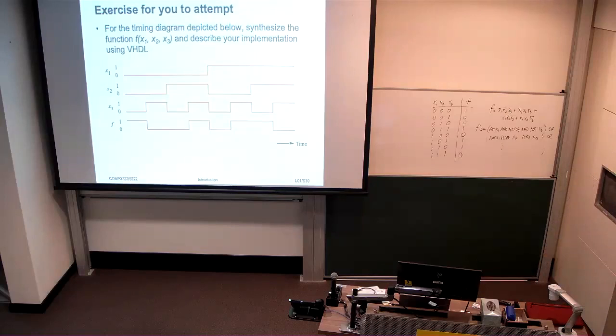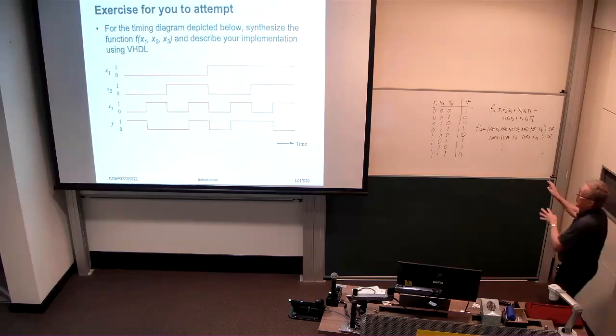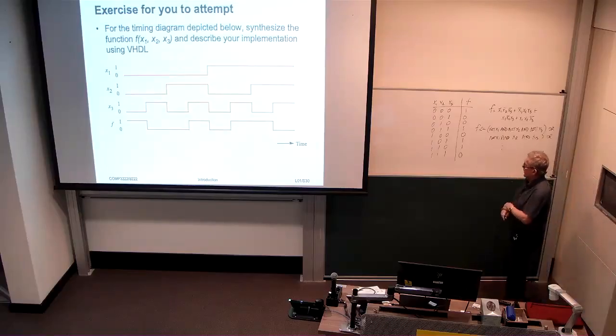The entity declaration in this case would be what? What ports do we have? And they're of mode in, and they're of type bit as far as we know at this stage. And we would have F as being an output bit, right? So I don't think we'll go into the details of writing that out.